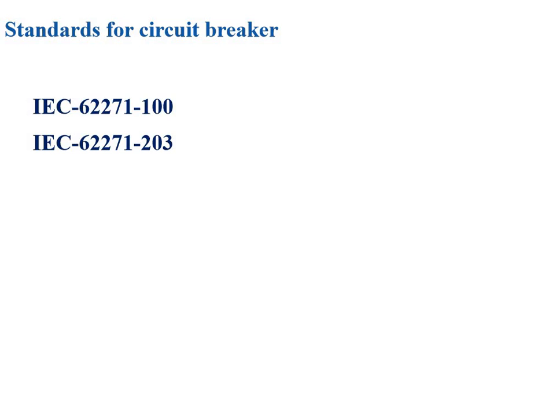The next standard is IEC 62271-203. This standard is used for the gas insulated metal enclosed switchgear for rated voltages above 52 kV. The next is IEC 62271-1, and this is used for the common clauses for high voltage switchgear and control gear standard.